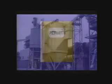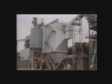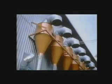During design, remember to check with your local air pollution control agency to obtain a permit. The agency can give you guidance for selecting an air cleaner. The major types of particulate air cleaners include fabric filter devices such as bag houses, electrostatic precipitators, and cyclone separators.